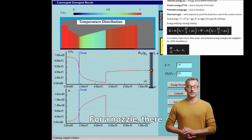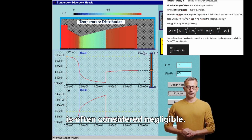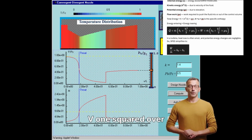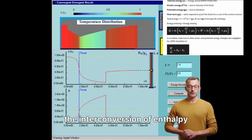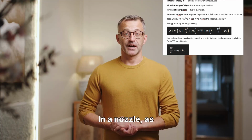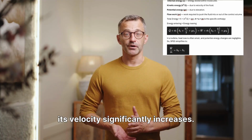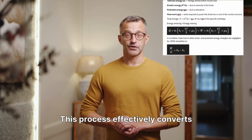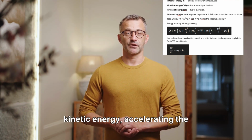For a nozzle, there is typically no work interaction, and heat transfer is often considered negligible. Therefore, the SFE simplifies to h1 plus V1 squared over 2 equals h2 plus V2 squared over 2, focusing on the interconversion of enthalpy and kinetic energy. In a nozzle, as the fluid flows through, its enthalpy decreases while its velocity significantly increases. This process effectively converts the thermal energy stored within the fluid into kinetic energy, accelerating the flow.